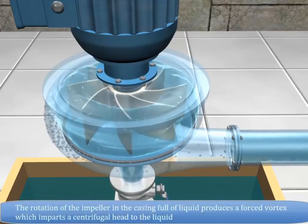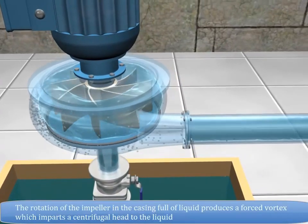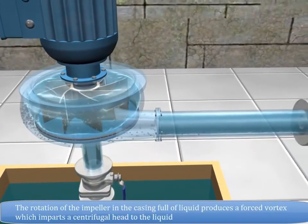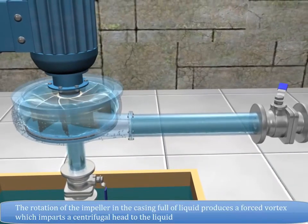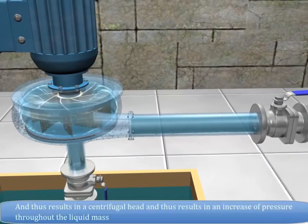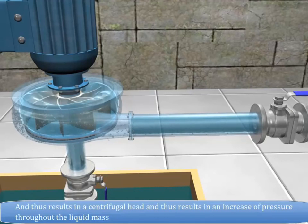The rotation of the impeller in the casing full of liquid produces a forced vortex which imparts a centrifugal head to the liquid and thus results in an increase of pressure throughout the liquid mass.